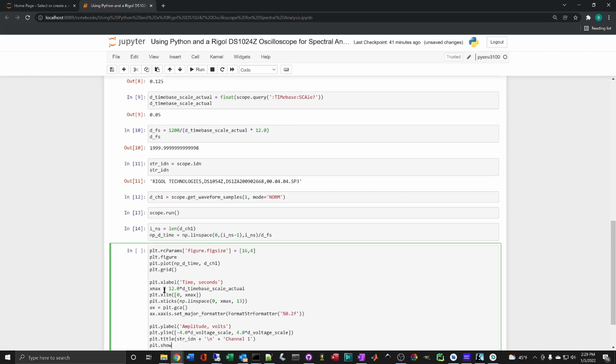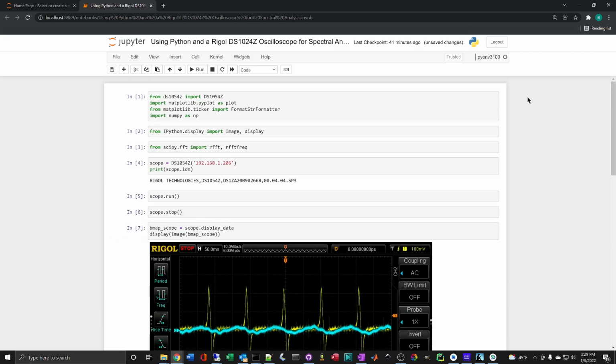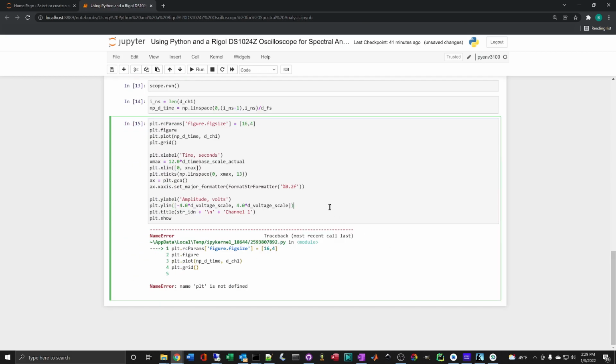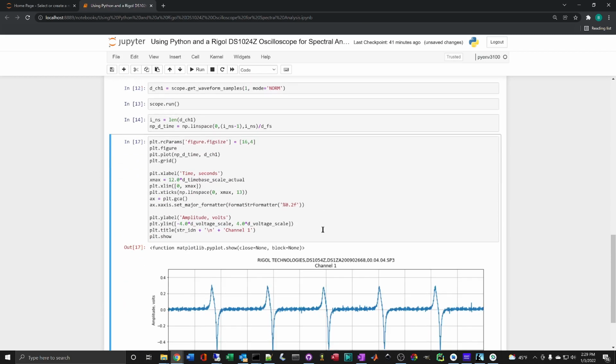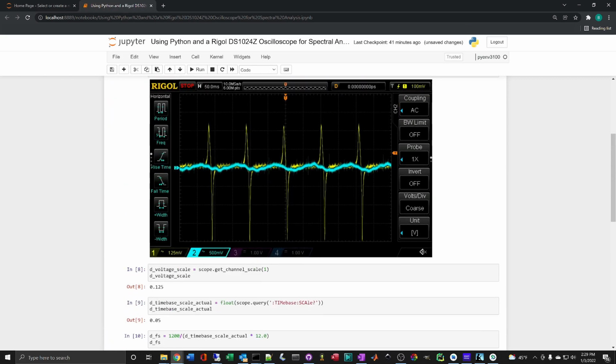Finally, we want to show this. It looks like I made a mistake up here. I did. Bad habit. All right. Except for that typo, things went very well, and it looks like we have our time base on here. And just a quick comparison, we want to be sure that we have our 12 divisions. We do. That goes out to 0.6 of a second, or 600 milliseconds. And it looks like our vertical scaling is roughly correct as well, matching what we have up here on the oscilloscope.